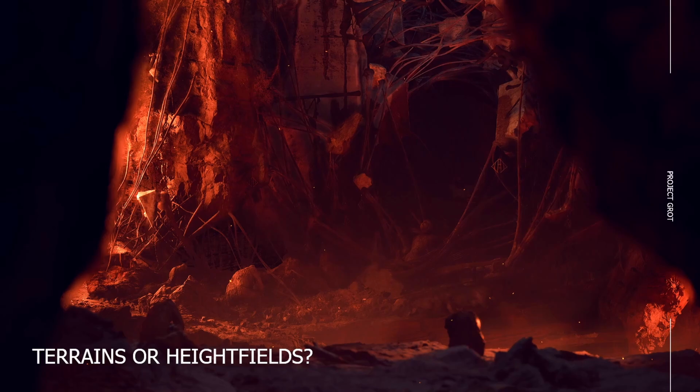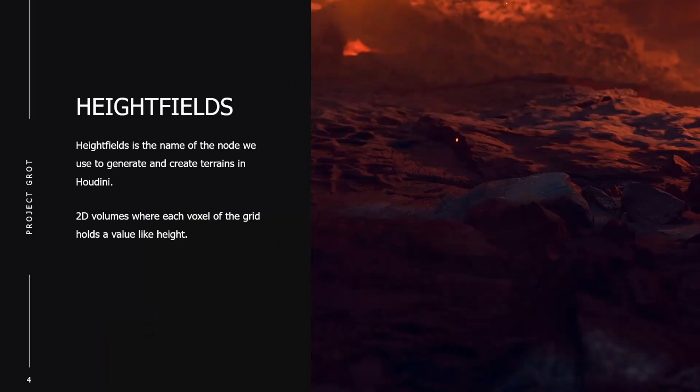Now, first of all, if you're new to this, terrains, heightfields, landscapes, what are all these terms? Essentially, you could say that they are quite similar in what they do, which is making a terrain. Heightfields is what we call it in Houdini. So if you would type in terrain in Houdini, you won't find anything close to it. We call them heightfields in Houdini. So these are the names of the nodes we will use in a moment as well. In more technical terms, these are 2D volumes where each voxel or the grid basically has a certain value. So we have a 2D plane, and you can say they have pixels, and each pixel represents a certain value, like the height, for example.